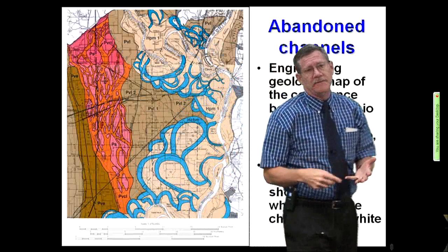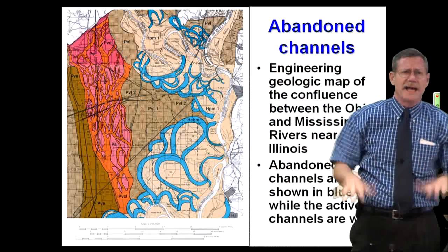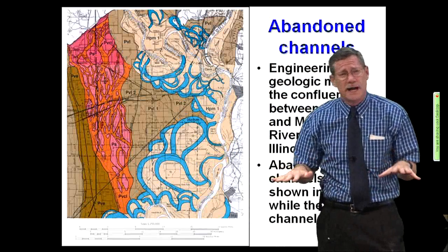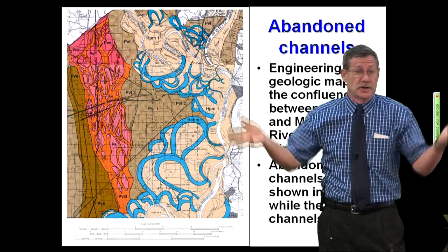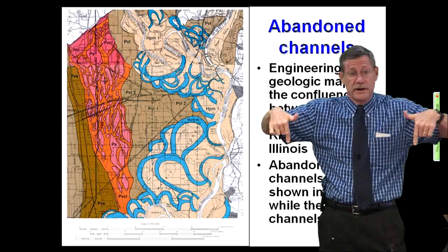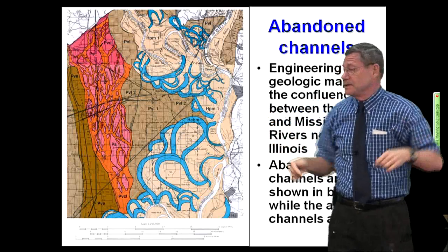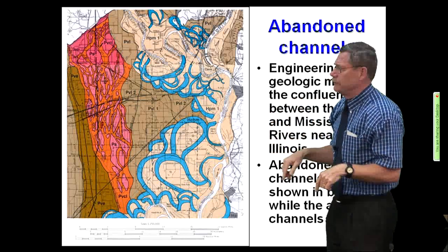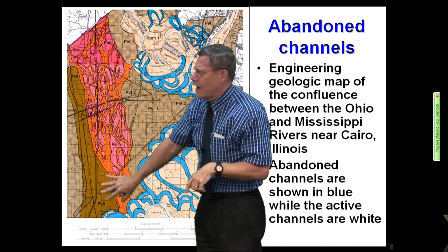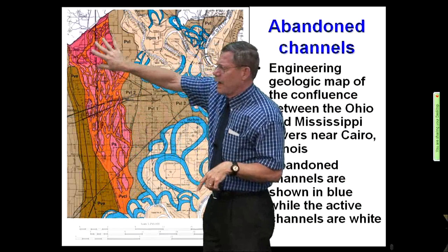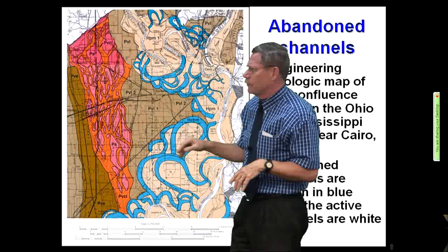Anywhere from 75 to 150 feet deep, you got lag gravels. Gorgeous lag gravels. Ain't no gravels anywhere in the state of Louisiana that are exposed. They're all buried under the Holocene. So you have to have deep piles going down into them. So we can use these for aggregate sources. Of course, they're not great for agriculture because they're not fine-grained enough. They lose water pretty quickly.